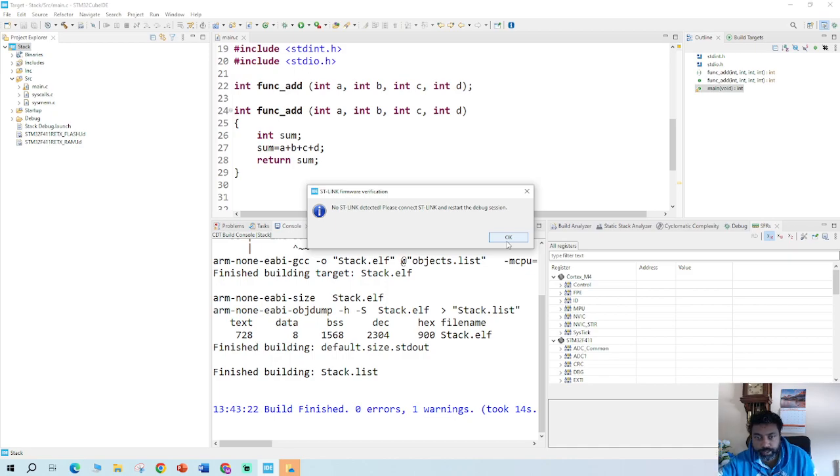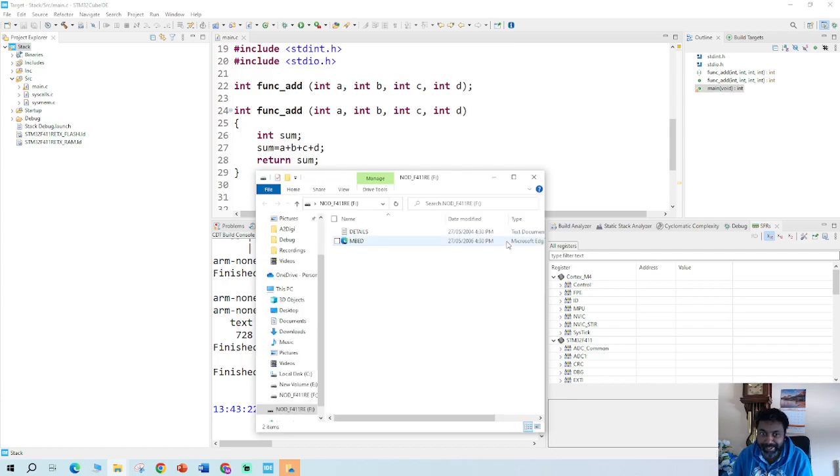It's saying there is no ST-Link detected because we chose the ST-Link, and that's because I unplugged the USB cable and left the target board unplugged, so I'm reconnecting to initialize that step. Yeah, that's the happy noise, the little ding ding ding, which is really good.